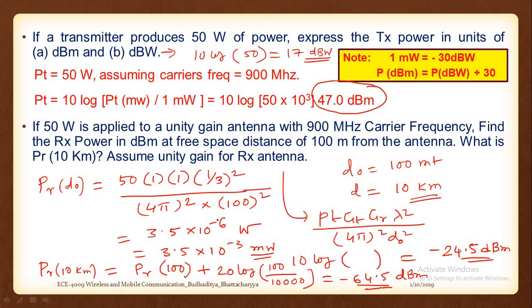It's not about the final outcome, it's understanding the problem. We are trying to measure at 10 kilometers, but in order to use the free space model, we need a reference distance. In this case, the reference distance is 100 meters. We are taking that as a reference and then moving ahead in making the measurement. Now D can be anything, but the reference distance or the reference power is always minus 24 dB. Understood? That is the calculation behind this.